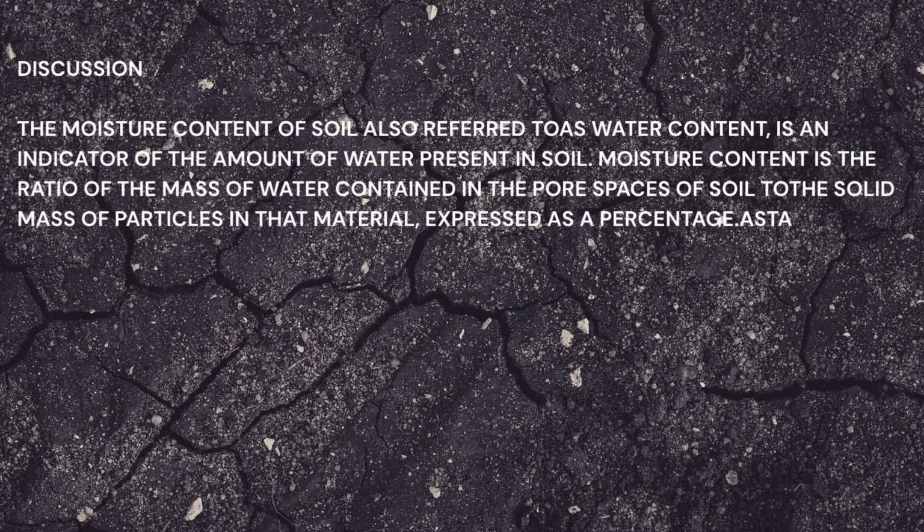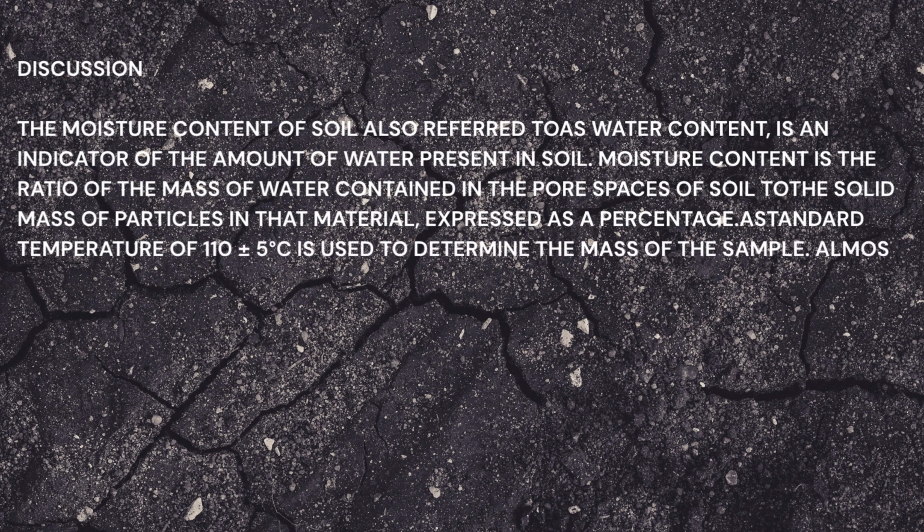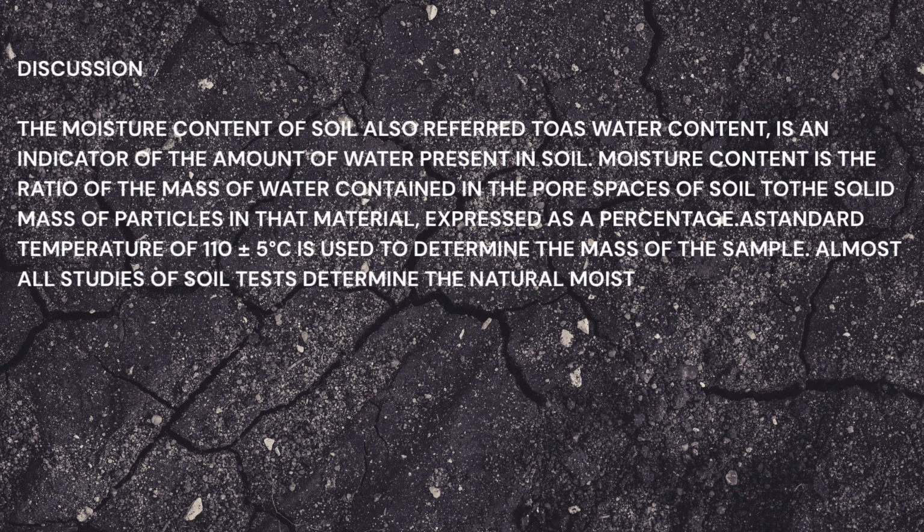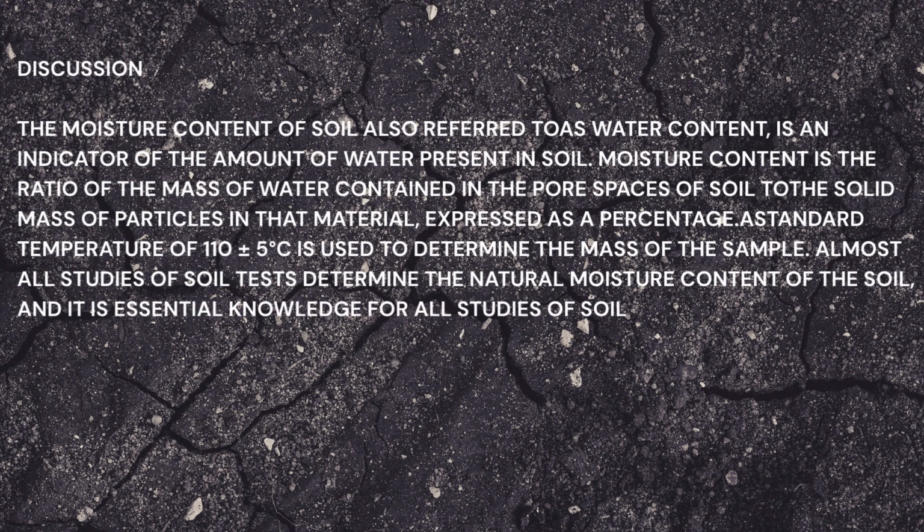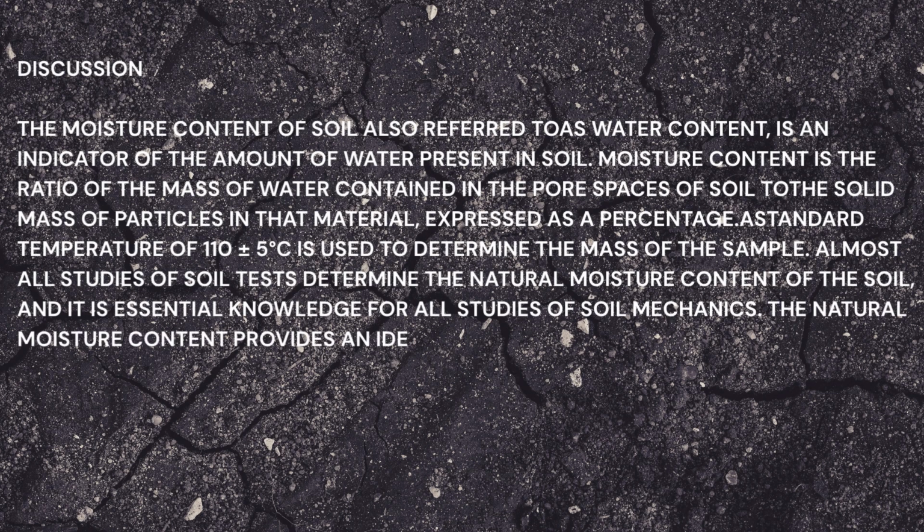A standard temperature of 110 plus or minus 5 degrees Celsius is used to determine the mass of the sample. Almost all studies of soil tests determine the natural moisture content of the soil, and it is essential knowledge for all studies of soil mechanics. The natural moisture content provides an idea of the state of the soil in the field.